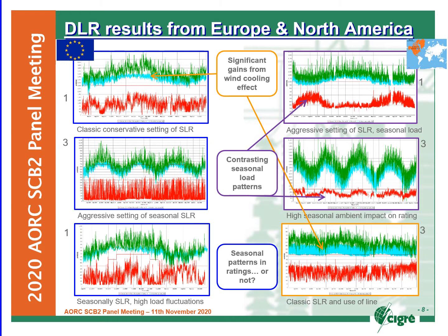One last thing to note is that in all cases, the load does not exceed the green line. To ensure an N-1 safe operation, typically for a radial line, you don't want to exceed 50% of the line rating, and for a meshed grid, rule of thumb is that you don't want to exceed around 70 to 80% of the line rating. The top left and bottom right in particular, you can see they adhere to this classical operational approach. However, some cases, like the bottom left, the load exceeds the static line rating, but it does not and should not exceed the green line, which is the true capacity of the line.